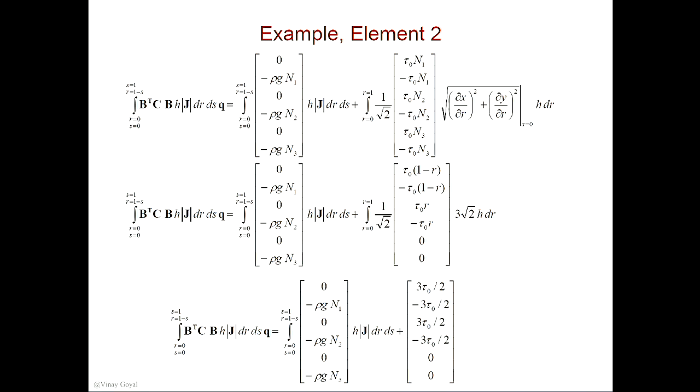When you do that, things simplify a little bit. This shape function simplifies a little bit, and you get these two to be 0. That makes sense because node number 3 is not involved in any way on what's going on in this edge, right? So automatically finite elements is capturing that.